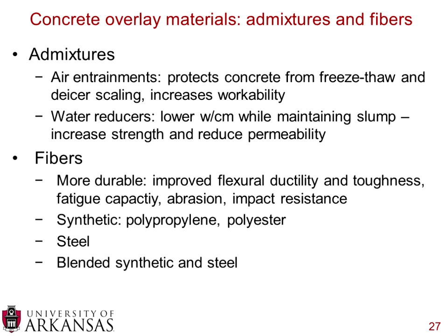It also prevents the pavement from deteriorating under de-icer scaling. So if you're in northern climates where you use a lot of de-icing agents, you can reduce the amount of scaling that could be associated with that using air entrainers. And the side benefit during construction is that you're able to increase your workability. The second admixture, water reducers, allow you to lower your water to cementitious ratio while maintaining your slump, and you can also increase your strength and reduce your permeability.